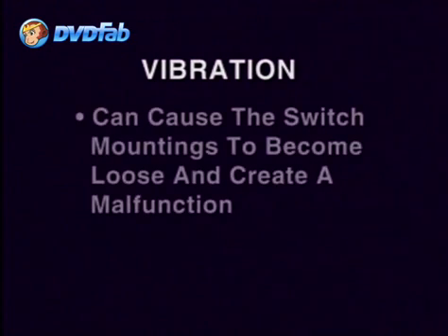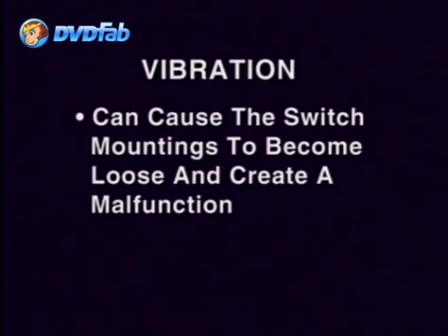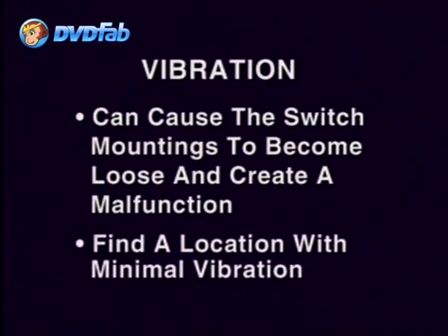Extreme vibration, such as that experienced in stamping presses, may cause the limit switch and mountings to become loose and create a malfunction. Here, the solution is to mount the switch in a location where the vibration is minimal or away from the section that creates most of the vibration.